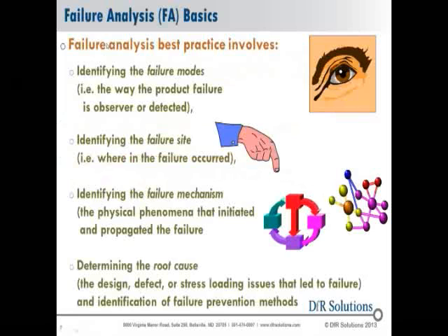So failure analysis best practices involve identifying the failure mode, which we call the way a product fails, or is observed or detected. And then you want to identify the specific failure site of what failed or what occurred. And once you have that, you want to focus on understanding the failure mechanism, the cause of events or phenomena that led to the failure being initiated and propagated until it turned into a full failure.